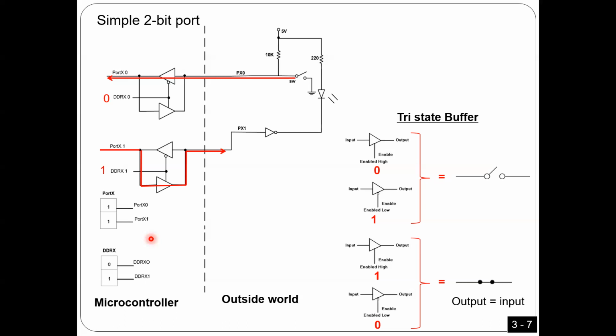So what we did is we defined all these addresses using equate. You remember equate? We already defined this. So here we have DDRA, and then we put the address. We have DDRB, equate, and put the address, and so on. I did it this way so that instead of using numbers, I'm going to use an English name. But keep in mind, this English name is going to be replaced by the address, by a number. You understand what I'm saying, guys?